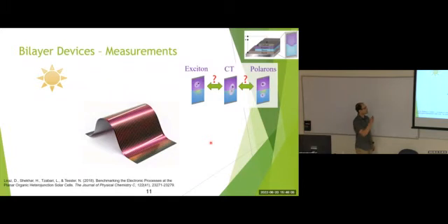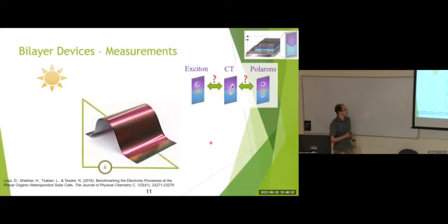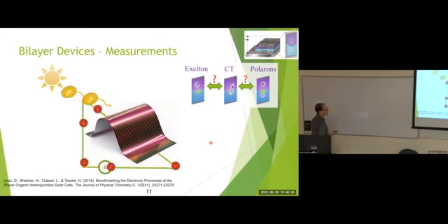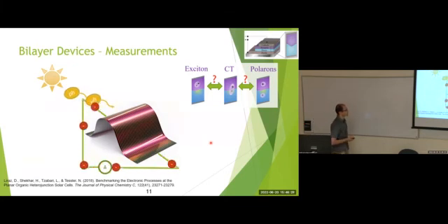So when a photon hits our device, it should generate an electron in the external circuit. However, because of losses, sometimes there is a photon that won't create any electron. And basically, the quantum efficiency is the ratio between electrons in the external circuit versus the photons hitting the device.